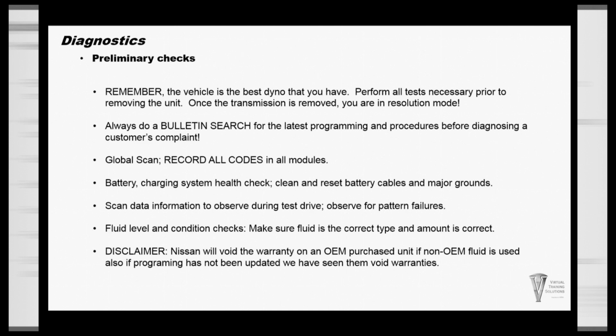Battery and charging system health check. You want to clean the battery, reset the battery cables, and clean the major grounds. Make sure we do voltage checks on the battery and the charging system before we remove this transmission, or before we get too deep into the diagnostics. It's got to be one of the first things we do on any vehicle.